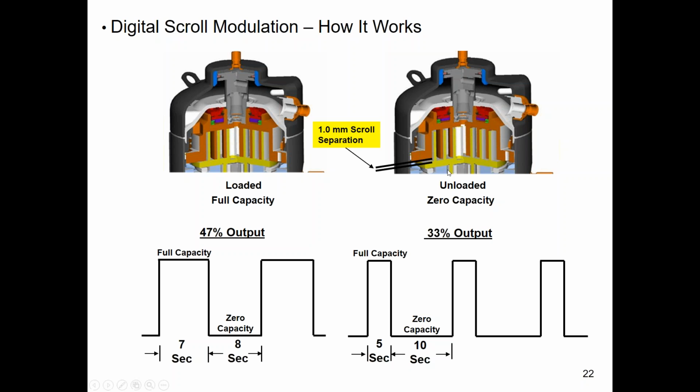Especially in this case, if he already has an oil problem, obviously it's going to happen again and again. Anything you do to fix it, it's just going to happen again. And that's usually what happens. You have your first compressor failure because of loss of oil and slugging. You're washing the oil out of the compressor and it's storing out in the system. Then you lose that compressor, put a new compressor in, and guess what? That oil's still out in the system.